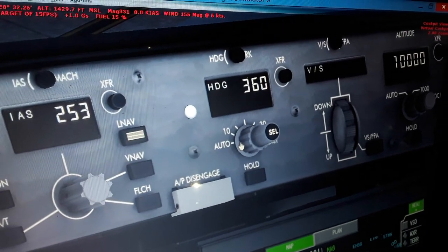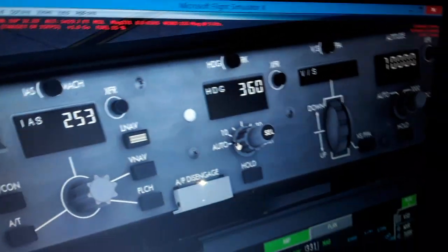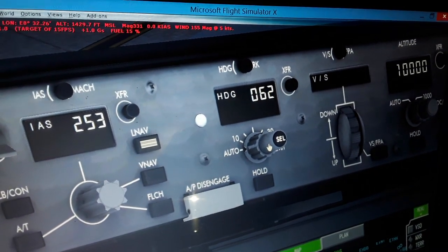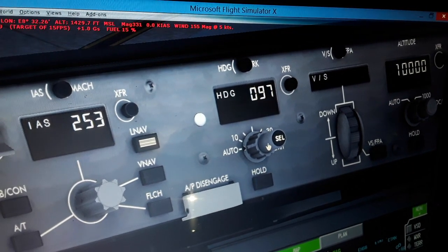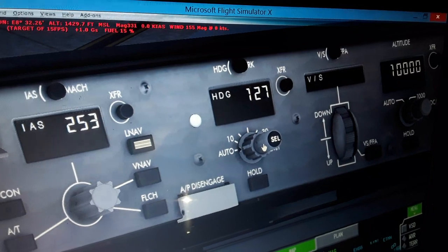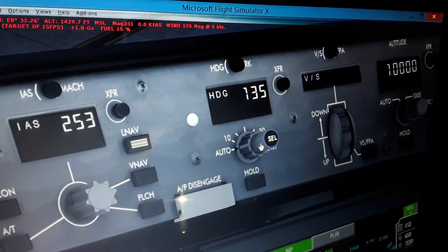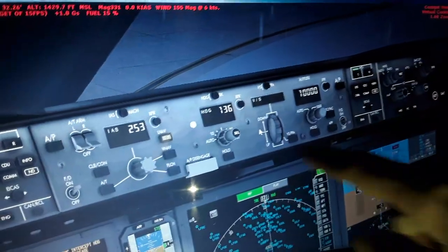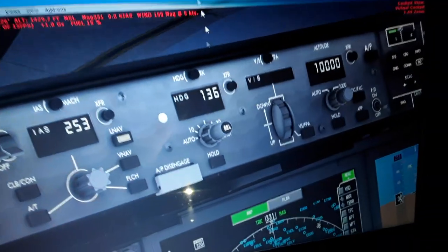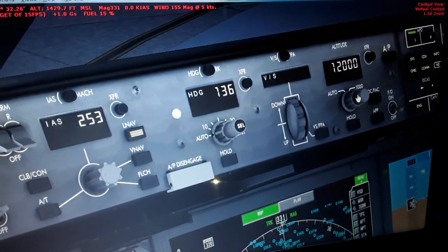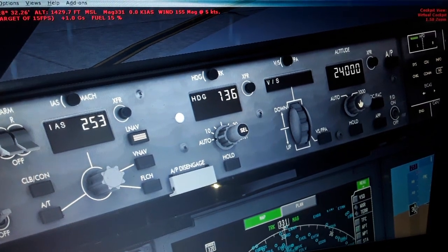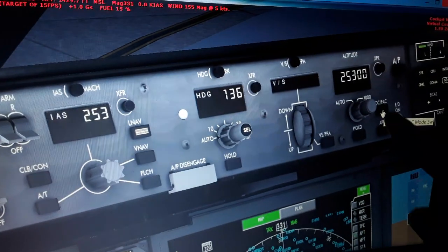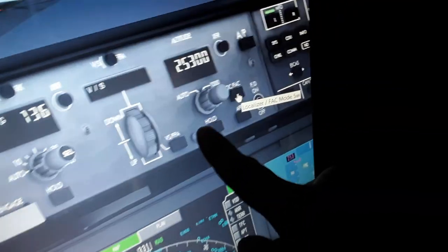We have the bank angle in flight, so this is the heading guidance. Magnetic north pole heading, we're gonna say 136 degrees. Same as the runway of the LSZH airport, Zurich International Airport, runway 14. So we're gonna have 136 degrees for that. We have also the altitude here, the altitude setting, vertical speed also. So the altitude, I'm gonna set thousands, 35,000, 100, 200, 300. VOR localizer, approach, VOR localizer, hold vertical speed over here.